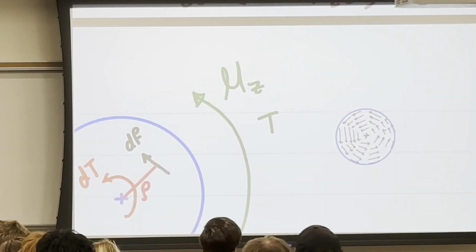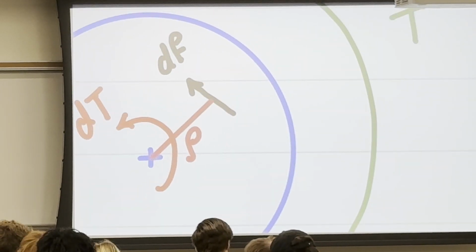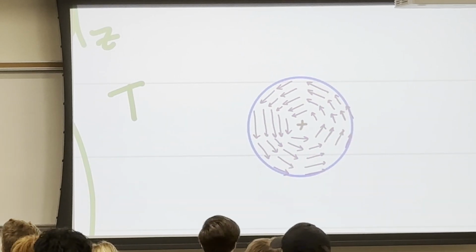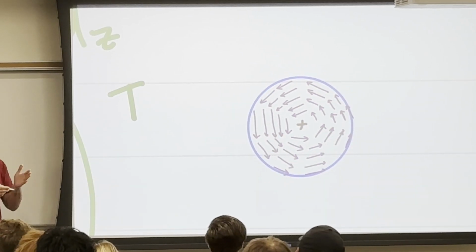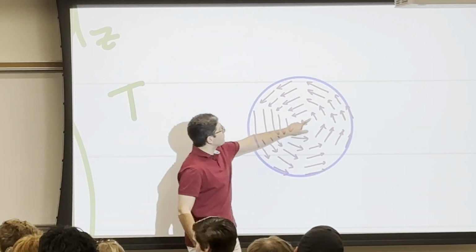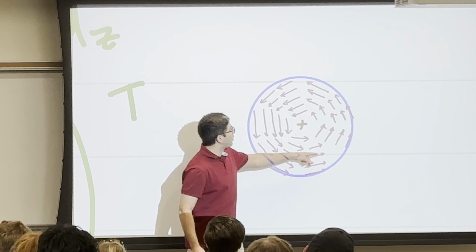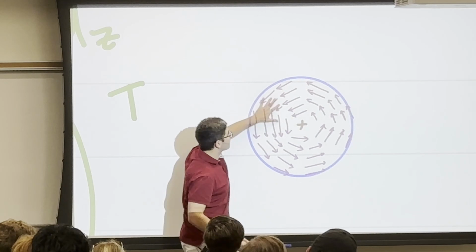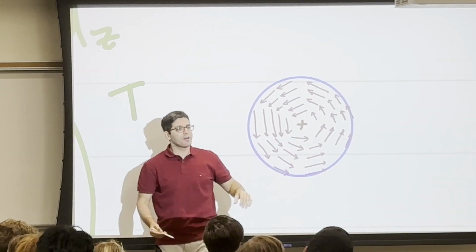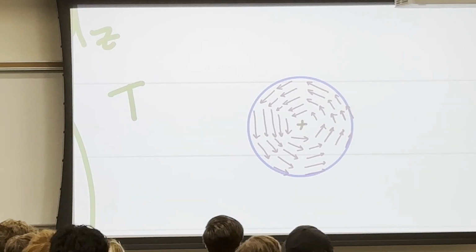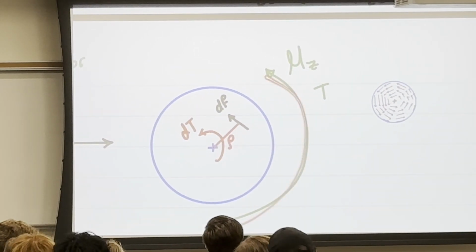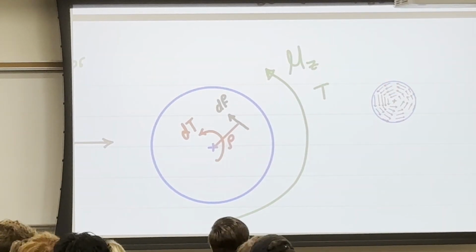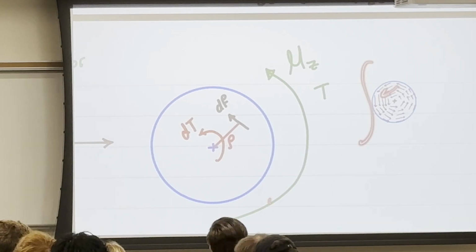So here I just took one of them and multiplied by rho, and that's why I call it dF. The reason I'm calling it dF is that, as you all know from calculus, when I add up the dF's I want to integrate. So one force here is called dF, but if I want to take all the forces, I'm going to take the summation of dF. That's when I will get everything. And when I take the summation of dF times the rho of each one, that's how I will end up with the Mz. So these small dF's are just a breakup of the Mz. That's just basic calculus. And when I integrate those, I'm going to end up with Mz.